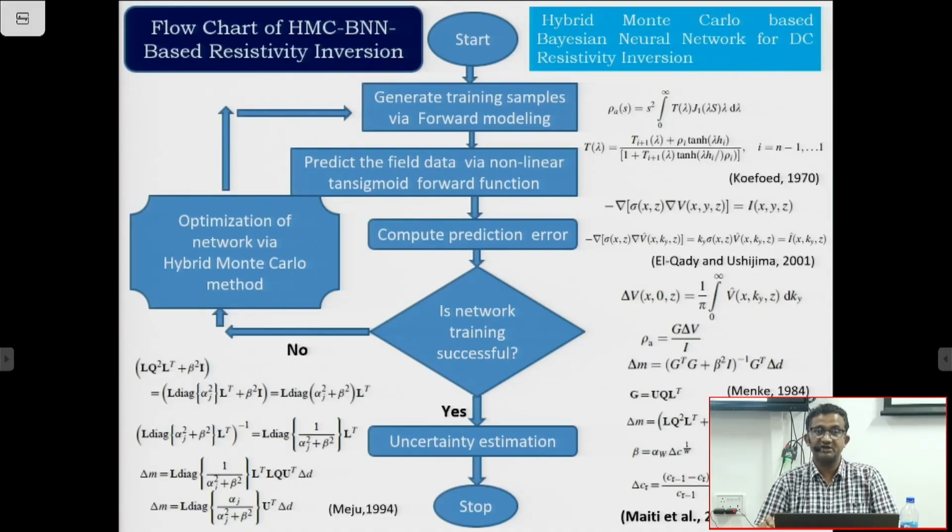But here we are talking about the inverse problem with a VES sounding data set, where the concept is 1D, meaning we are only looking at how resistivity varies longitudinally, from the surface to the inside of the earth. And from that we can have a good and quick solution about how our layers are.